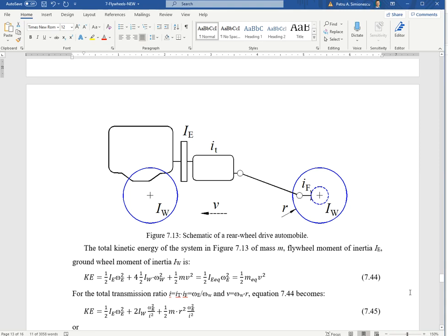Everybody knows if you're driving an empty vehicle, you can accelerate faster. Not that you can drive at a higher top speed; steady state speed is not affected much, maybe by rolling resistance, which is a function of the weight. Otherwise, who's getting to the maximum speed their vehicle is capable of anyway? But in terms of accelerating properties, replacing the flywheel on the crankshaft with a smaller one is like driving a lighter vehicle with the same engine.